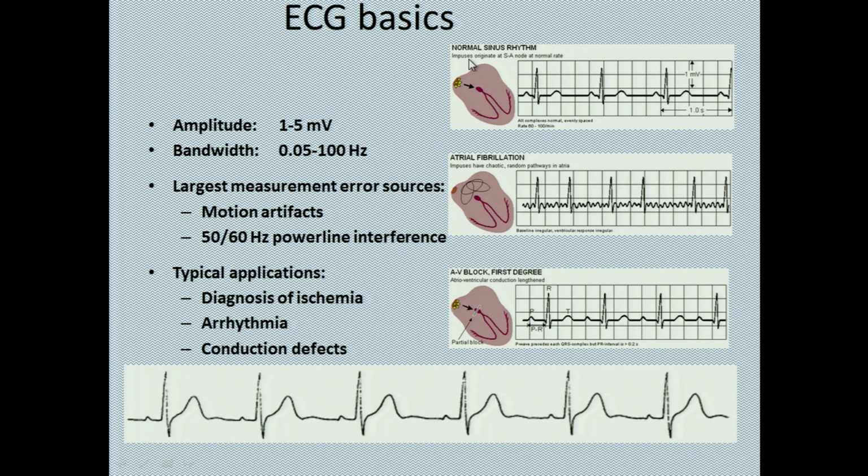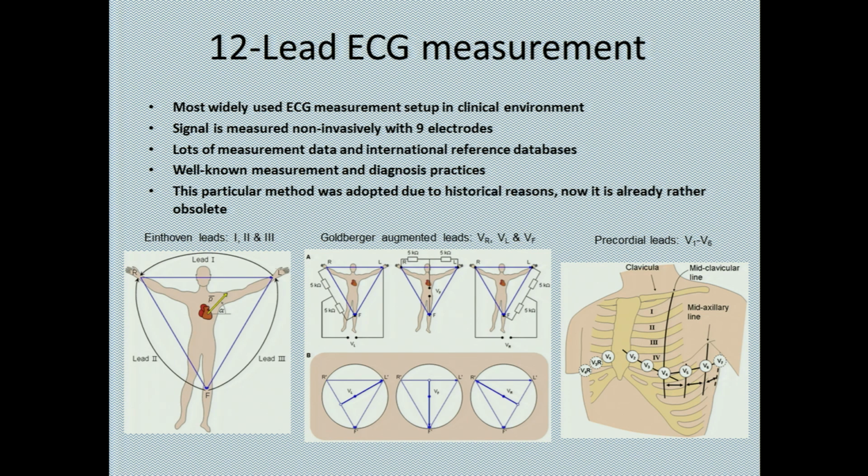So, yeah, we know these are all the details, we have to skip now, when time permits we will come back. And we are going to use only 3 leads. We will put 2 in the chest, 1 on the ground, and that will be connected. The 2 go to your op-amp; we will use a differential or instrumentation op-amp. So you will have 2 inputs, they come from here, and then the ground.